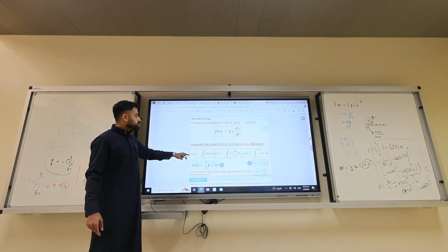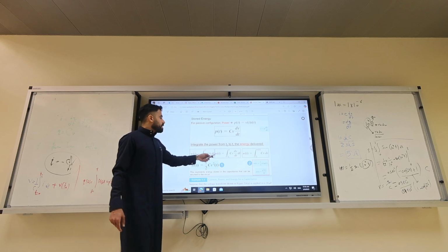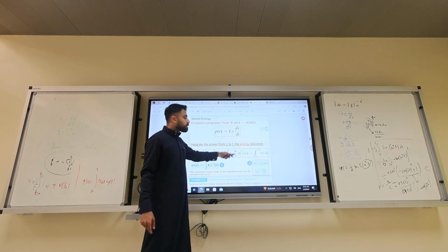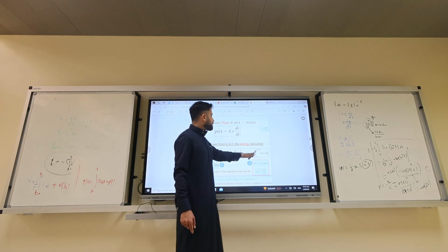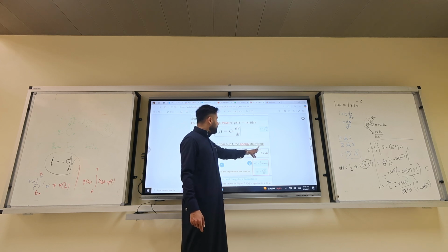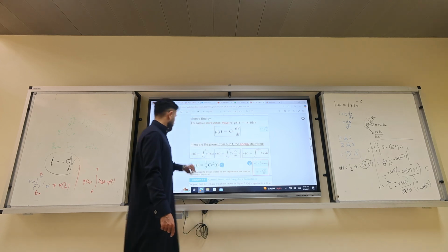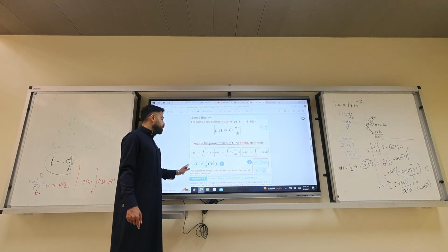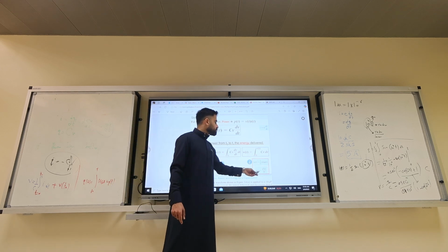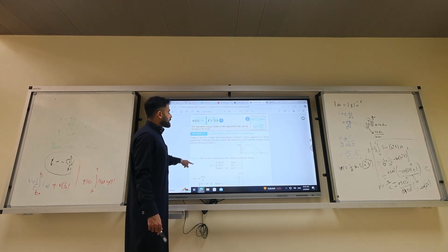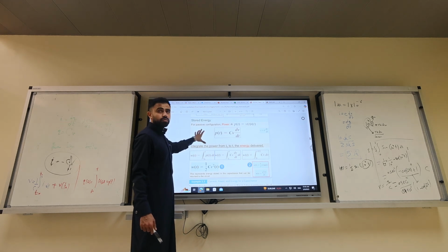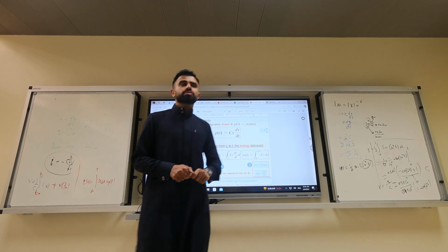Now, energy is the integral of power, which is C V times dV/dt. dt will cancel with dt. Then you will have the integral from 0 to the variable v of t times C V. Ultimately, you will have the equation half C V squared for the energy. If you write it as a function of charge, it's q squared over 2C. Okay? There is an example. We will stop here. Next time we'll start with the energy. Now at least we're back on track.